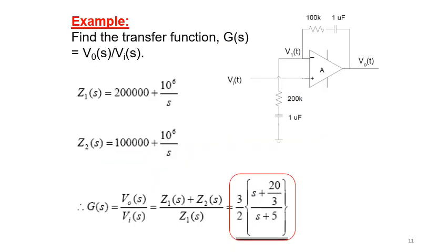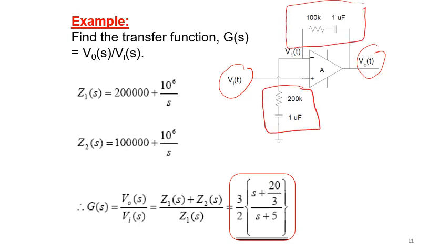So hopefully now you find that the operational amplifier is something easy to deal with. All I need to know is identifying the impedances, because I can apply the transfer function directly. You want to know Vout over Vin. We know the equation. So all I need to do is prepare Z2 and Z1. This is going to be Z2 and this is Z1.